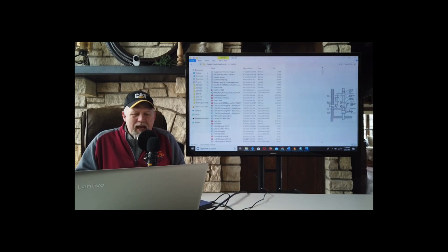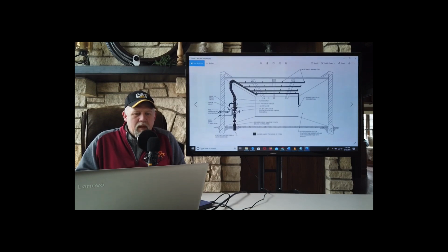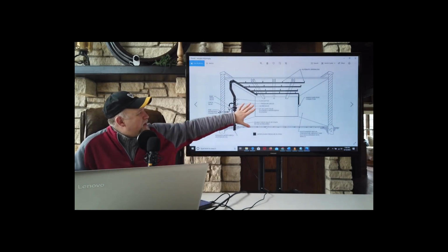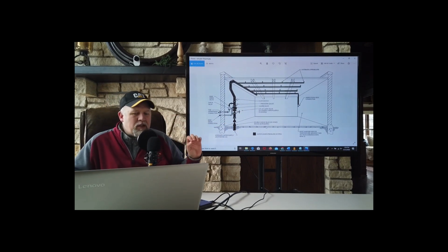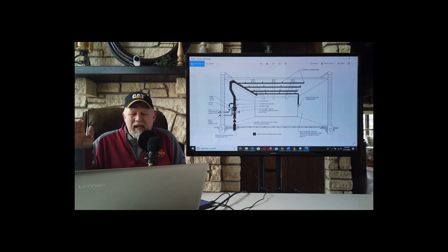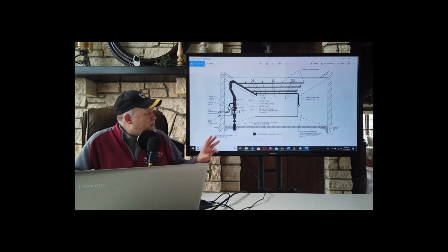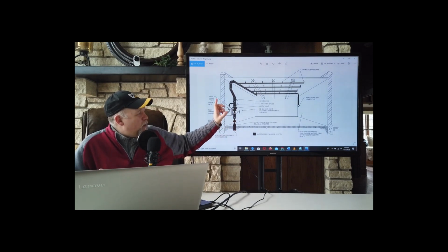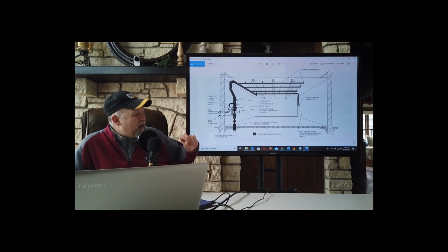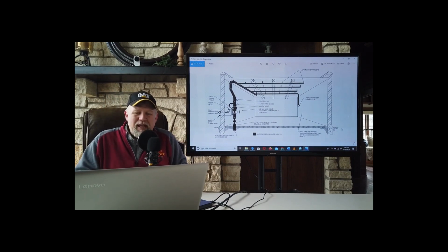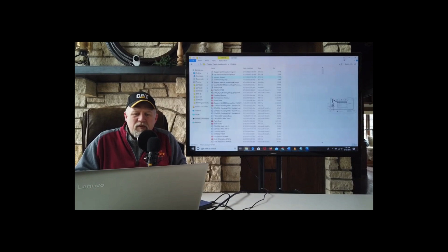All right, now if we look at the wet pipe diagram, this one has water throughout the entire system. And remember, there are wet and dry pipe systems, and then we are going to talk about wet and dry agents in a little bit. So the basic systems that use water can have a wet pipe always filled with water, or a dry pipe only filled with water after the air pressure has gone away. All right, now let's take a little closer look at these individual sprinkler heads.